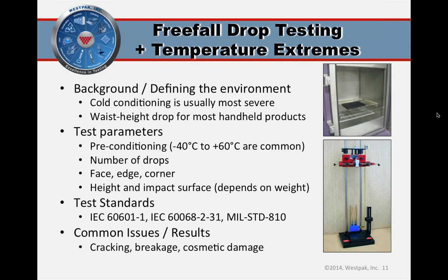So this is what we refer to again as free-fall drop testing at temperature extremes, and it should be differentiated or at least thought of differently than impact testing, which is basically what I call the catcher test, or some rigid body impacting the unit that you're talking about.